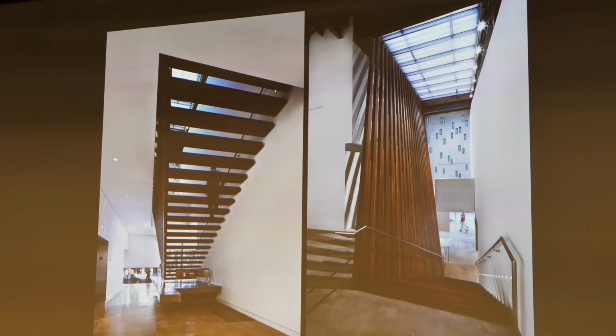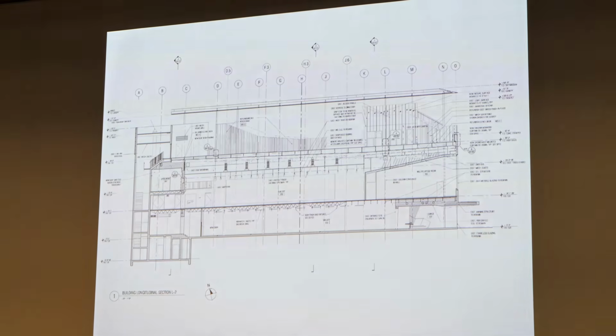The slope of that step is derived, and the angle going all the way up to the skylight of the side piece is set by the angle required by the tip of the nosing by code. In other words, your angle for your rise run is derived and carried out into the overall building itself.